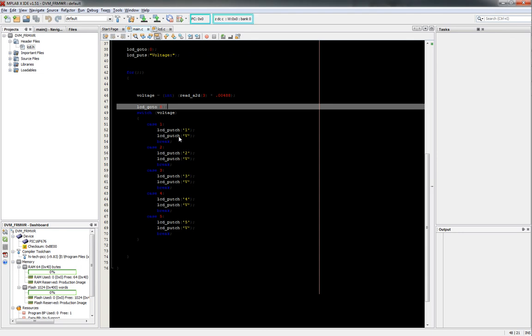It needs to be an ASCII coded character that it writes to the screen. If I straight away just throw the voltage in there as an integer and print it, it's going to convert that to hex and send that hex value. That means it's going to be a hexadecimal 1. Well, you'd have to look at your character map, and what does a hexadecimal 1 get you? It may get you some funky character if you send a hexadecimal 1 to the screen according to